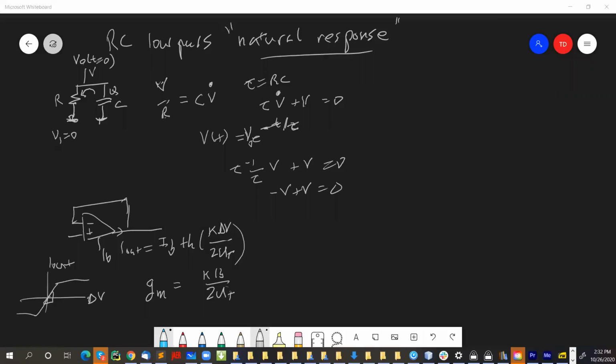So what's the question now? Do we want a very large gm, so a very large tau? So we want a very low gm. You want a small gm. If you want a long time constant, you want it to be weak, right? You want a small transconductance, high resistance. You want it to be slow, turn down the current. Makes sense, right? The smaller you make this bias current IB here, the slower it's going to be, right? Less current coming out. Yes, makes sense. Okay. It all is very reasonable. Yep. Thanks. Okay.